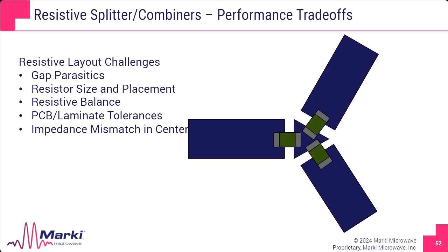What's the impedance of the triangle in the center? How do you handle the awful impedance mismatch in this middle section without having insane reflections? The answer is a full 3D EM simulation using HFSS or a couple days of an engineer's time.